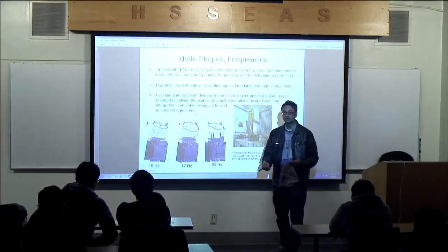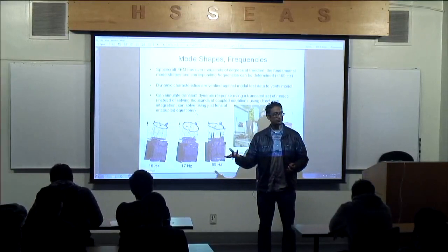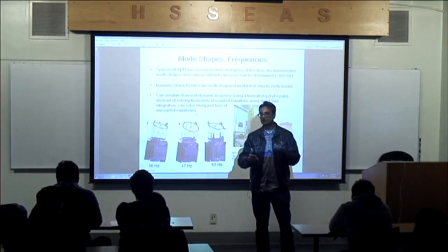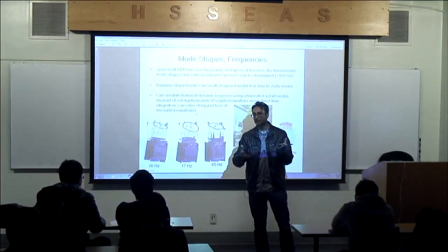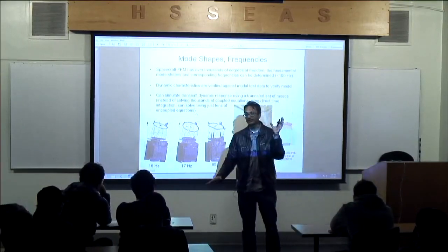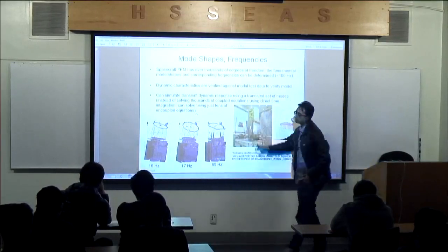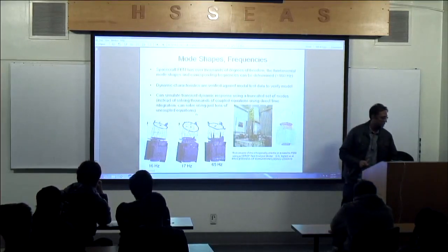And because I have 20 of them, how many unknowns do I have then? 20. As a function of time, I have to find. Instead of a million as a function of time, I have 20 of them. Isn't that computationally efficient? Oh, one more thing. They're all decoupled. I don't have to invert anything. And so you can see the strength of this approach right there.